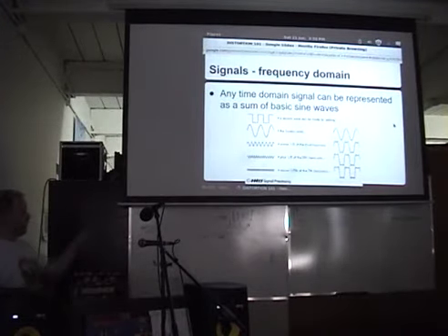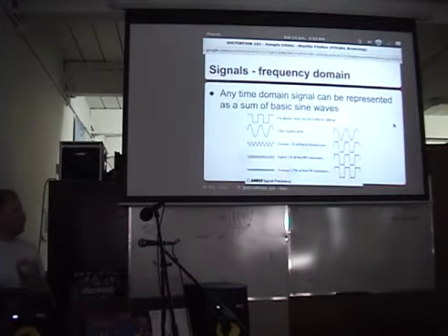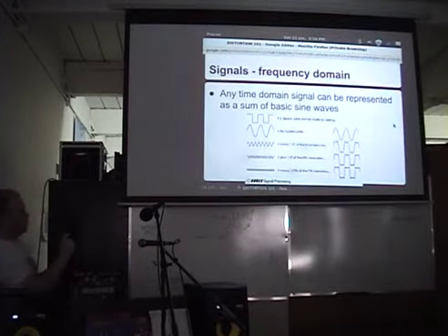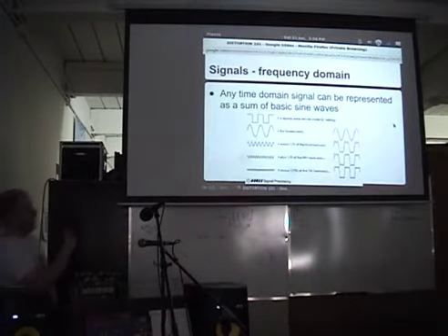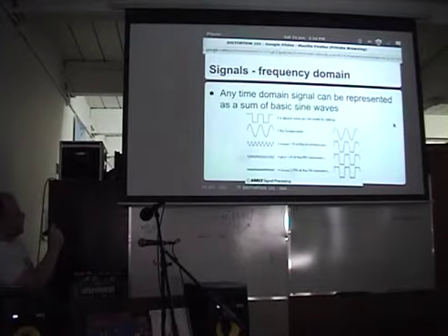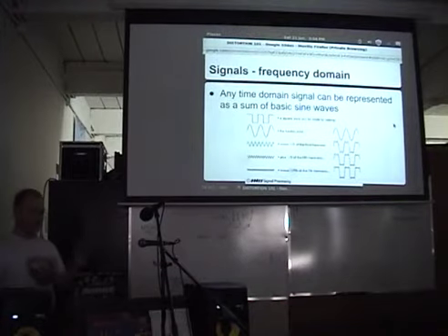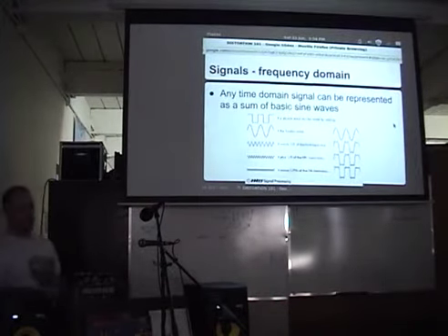If you have any time domain signal, some really smart French guy named Fourier found out you can compose this signal out of an infinite series of sinusoids mixed in at different levels. These are like pure tones. I couldn't do a nice pure tone like an 'ah', but it's a whole bunch of those added up. Notice this is the signal it's trying to make, and it has really sharp corners. You start out with something that's the same tone, and you keep adding higher and higher frequencies, and that output signal is getting crisper and crisper and approximating the square wave a lot better.